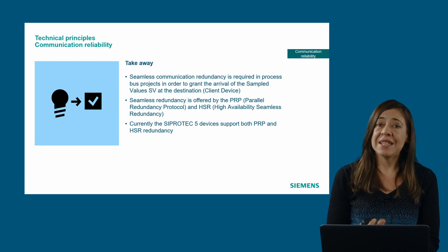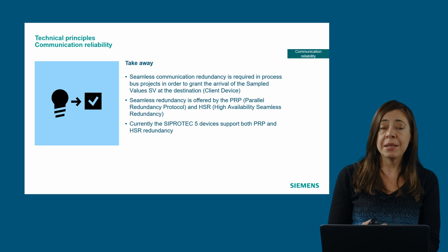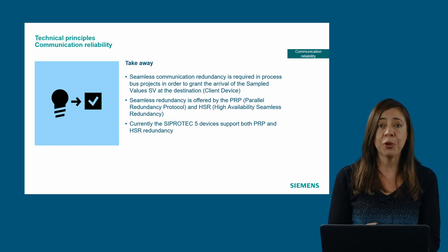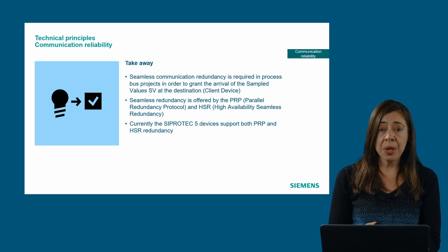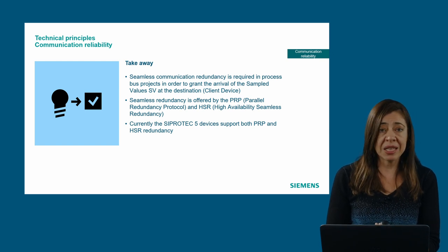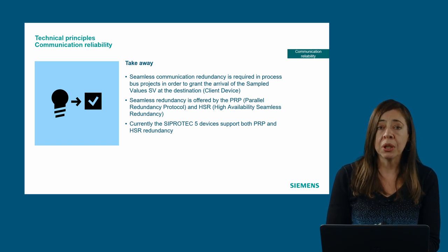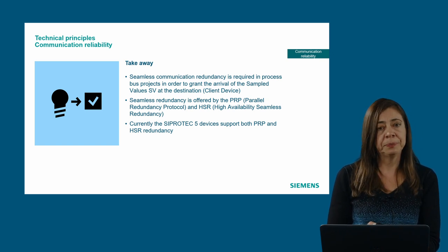So remember, the second key point of the technology is the seamless communication required for the process bus. To take away, the seamless redundancy can be granted with both PRP and HSR networks, and the SIPROTEC 5 devices support both of them.